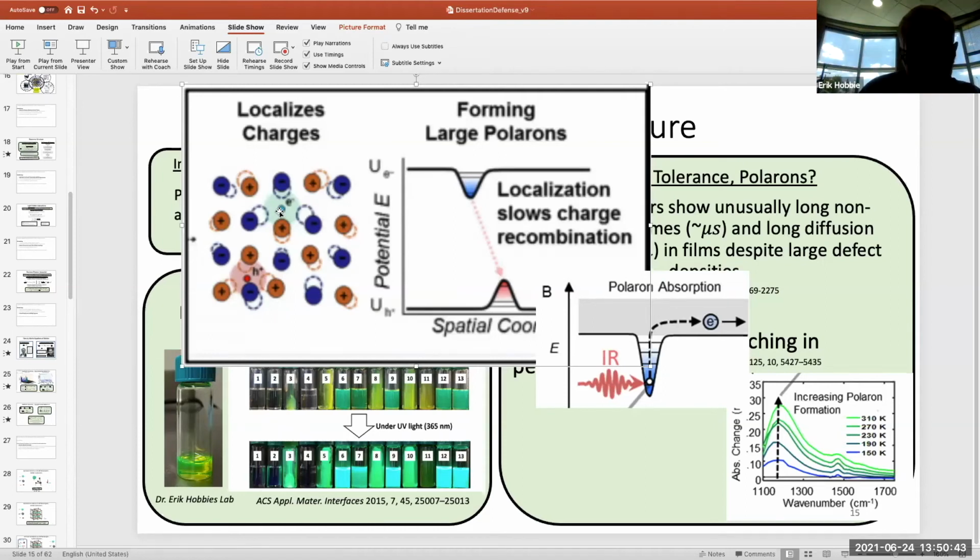Yes. So then I have another question that leads into this. As you and I know very well, these are notoriously soft materials. Is that a consequence of the ionic interaction, or is it a consequence of the perovskite structure itself? I think generally a large part of it is the ionic component, since they're polarizable. By definition they're able to move more easily, and their bonding is less directionally oriented. So if you apply stress, it's going to have more strain just because it can reorient more.